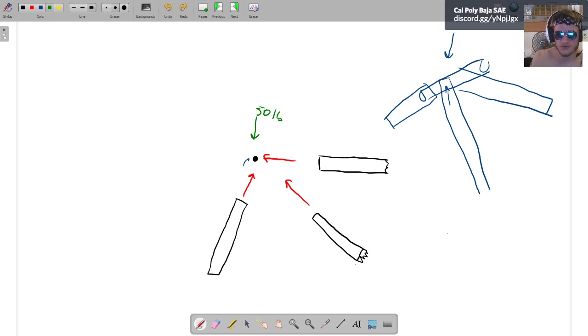Because if I draw this, imagining we remove this beam real quick, do our own free body diagram on that. If we're putting some force, let's say we have a force that way on the pin, that means we have to have an equal and opposite force on the beam here, and that's going to start to rotate this beam. Now we know that this beam can't rotate; it has to be only in tension or compression.